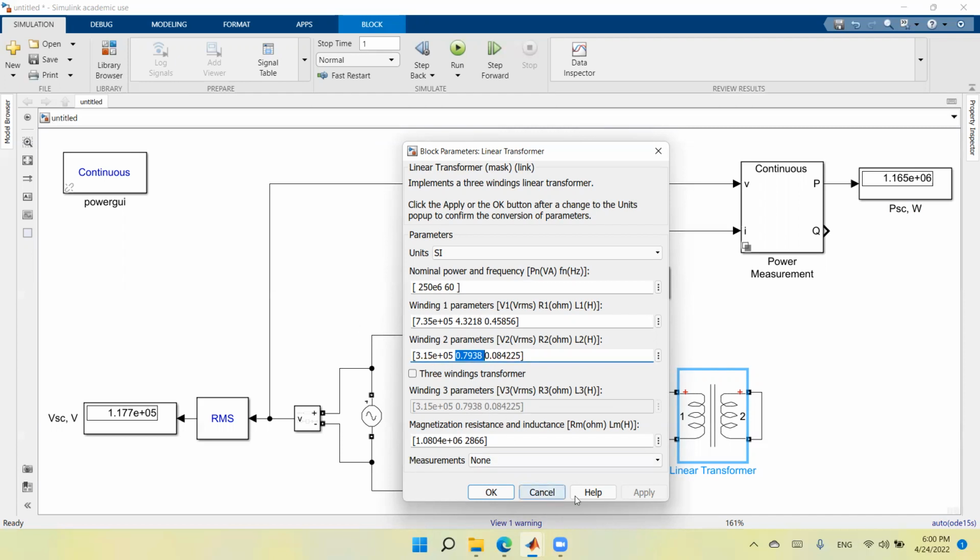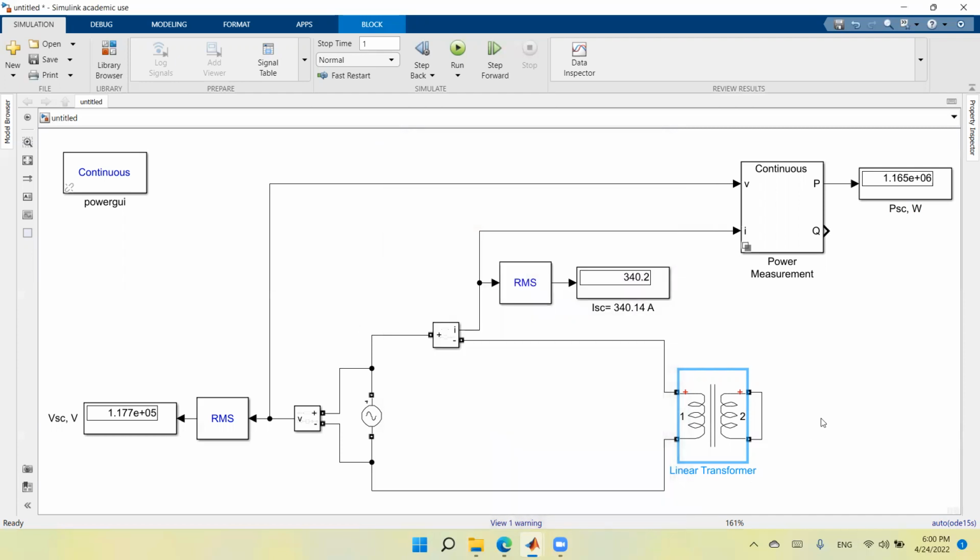So this is everything about the short circuit test. In real life, you need to be careful not to apply a voltage while the secondary side is closed, unless you are sure that this voltage is very small. We usually start with 8% or 10% of the rated voltage, and then you see whether you need to increase it in order to get the rated current, or decrease it if the current is more than the rated current.